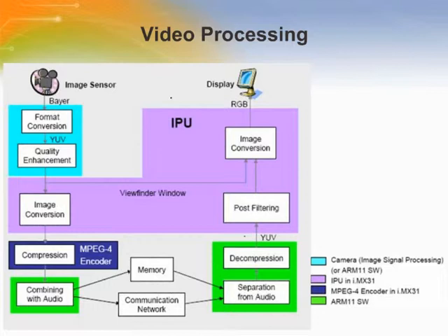It allows a camera preview function to be performed fully in hardware, allowing the CPU to be powered down in this stage. It performs post-filtering for MPEG-4, including deblocking and de-ringing, and it also performs in-loop deblocking for H.264 as specified in this standard. The preprocessor is part of the IPU, and it resizes the data and performs color space conversion. The preprocessor can send data to a small viewfinder display, which provides visual feedback to the user to ensure that the desired data is being captured.